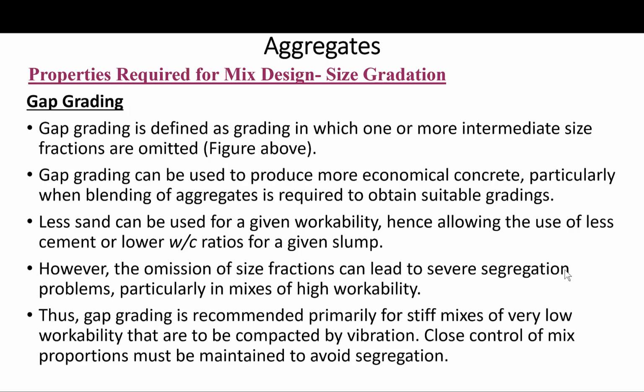In such cases, it is recommended that fine aggregates should be used that have at least 15% passing the 300 micrometer, number 50 sieve, and 3% or more passing the number 100, which is 150 micrometers.